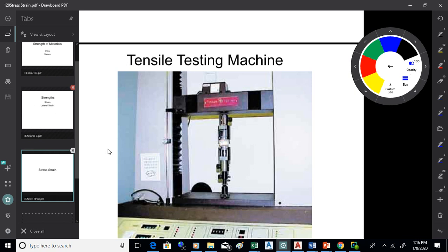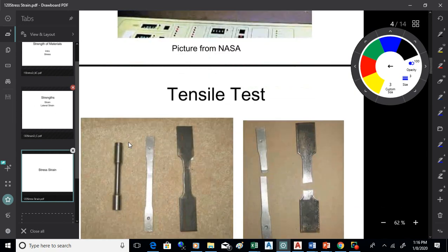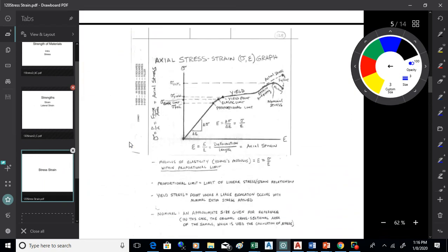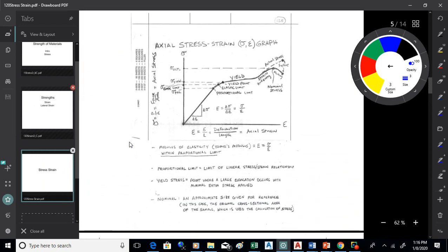And then also you could put something called an extensometer on there to measure the elongation of them as they fail, okay? And the machine will also measure the amount of force that's applied. So between that, what you're going to do is generate a stress-strain diagram, okay? So stress on one axis, the y-axis, strain on the other axis, the x-axis.